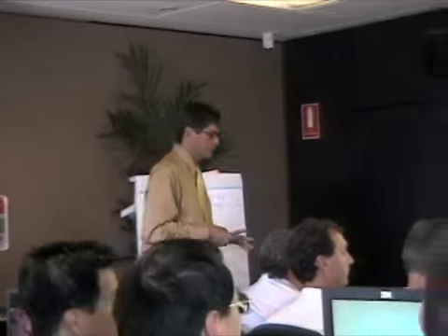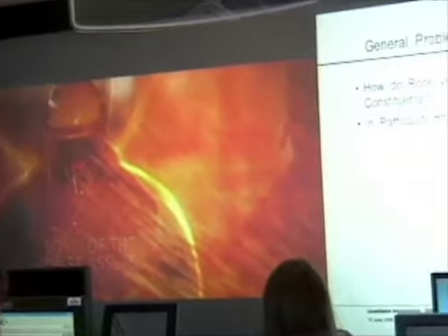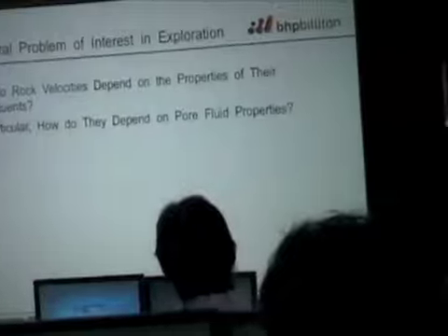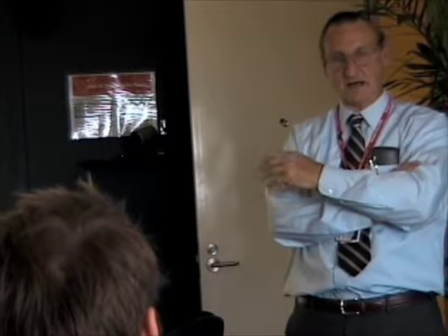Anybody else? Yeah, John. The isotropic porous material, this beta, given it's the matrix to the grain thing, in some sense it's a measure of how much of the space is taken up by pores. It should depend directly on porosity. It does depend on porosity, yeah, but indirectly, not directly. There's no easy way to formulate for any and all types of structures how that dependence goes.